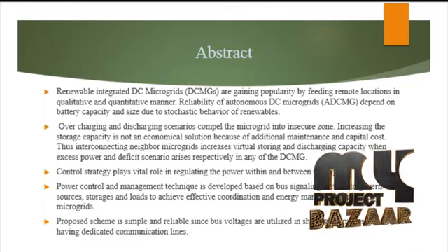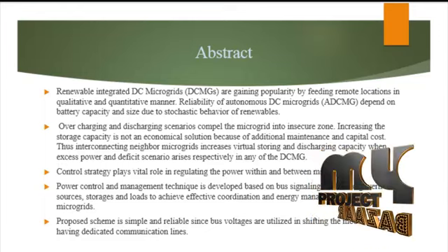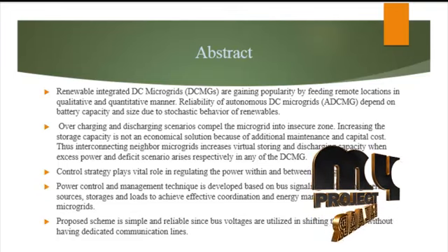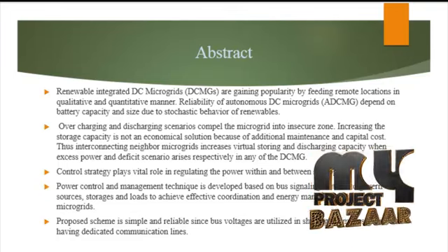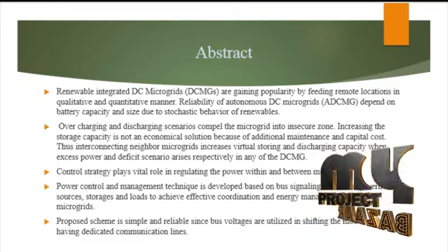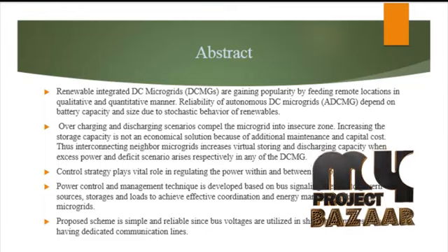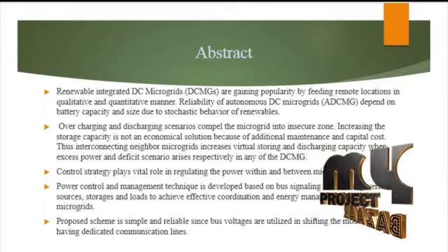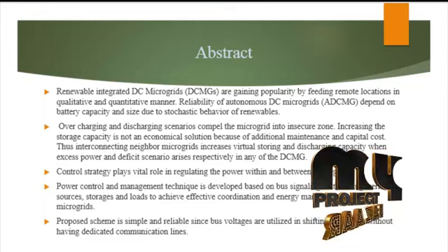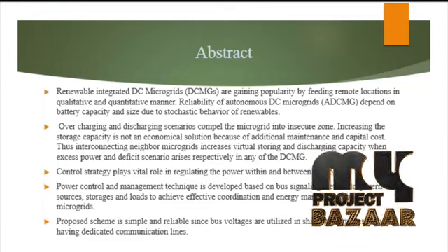The proposed system is simple and reliable, using bus voltage and shifting nodes without dedicated communication lines. The power control and management technique, the bus signal method, is applied to the storages and the loads to achieve effective coordination of the energy management between the microgrids.